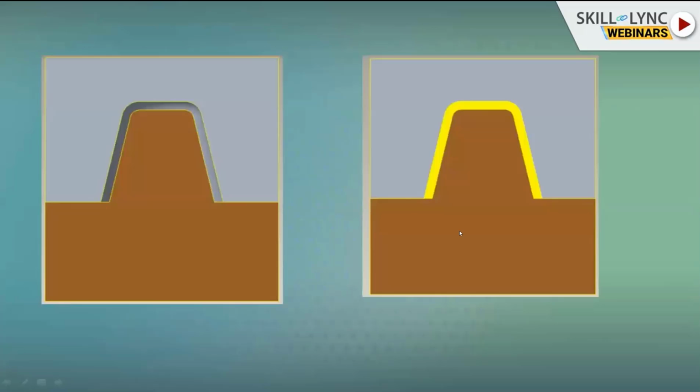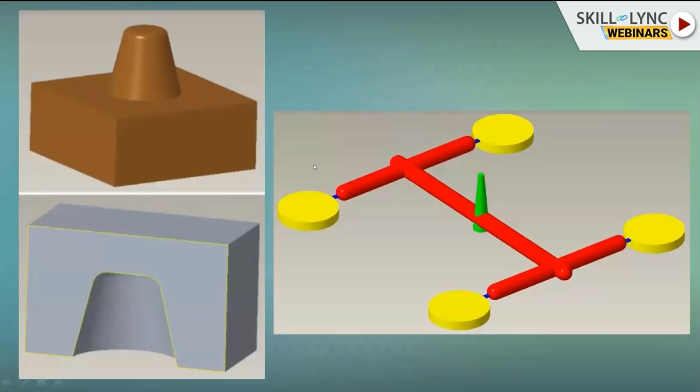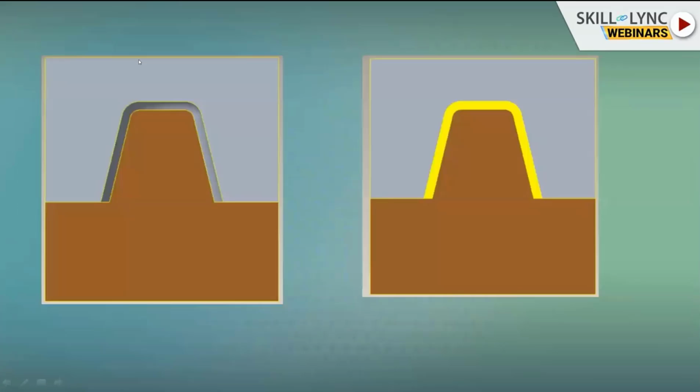So in the mold, the component will be in the core and cavity, and the cavity portion will move up. You can see that here the cavity will move up. During that, the component will get stuck in the core. So in order to remove this component, the ejection system will be there. As I showed in the mold base, the ejection system will work and eject the plastic component out.